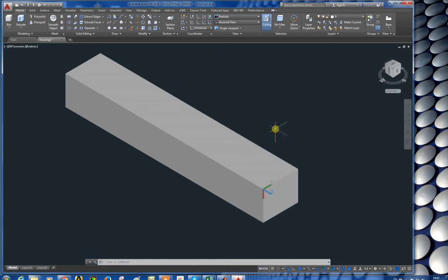We'll see the advantage of this at a later point. Also, AutoCAD has a unique feature in that you can toggle dynamic UCS. What that means is, if I'm drawing complicated objects and I want to draw on any plane, the UCS automatically changes. It's always dynamic. It's going to adapt to the plane I want to draw on. We're going to understand that at a later point.